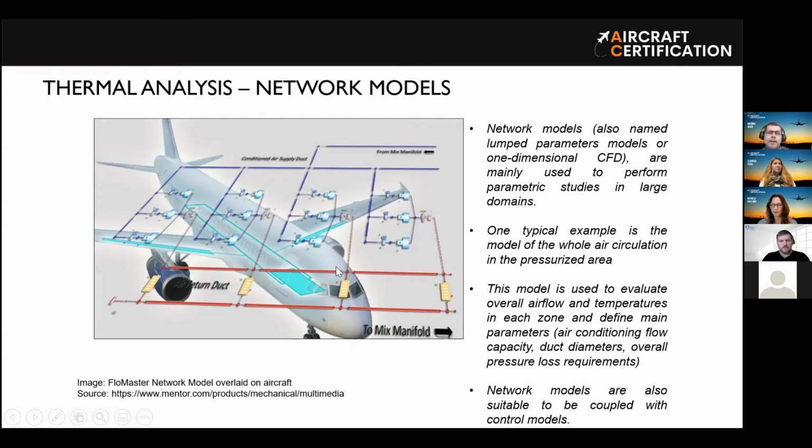and then the idea is that in the most important locations we place some nodes, and then we use thermodynamic equations, related to the pressure drop of the air, and also the heat transfer equations, to calculate how the pressure, the temperature and the airflow will change from one node to the other.